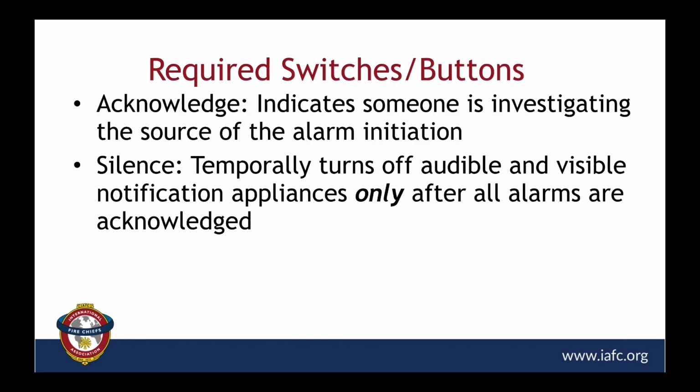And we'll review this one more time. So here are our required switches and buttons. On that acknowledge, what does that mean? When you hit the acknowledge, what you're saying is that somebody's investigating the source of the alarm initiation. And then the silence will temporarily turn off the audible and visible notification appliances once you've gone through the acknowledge. So it's a process of just going through some steps.